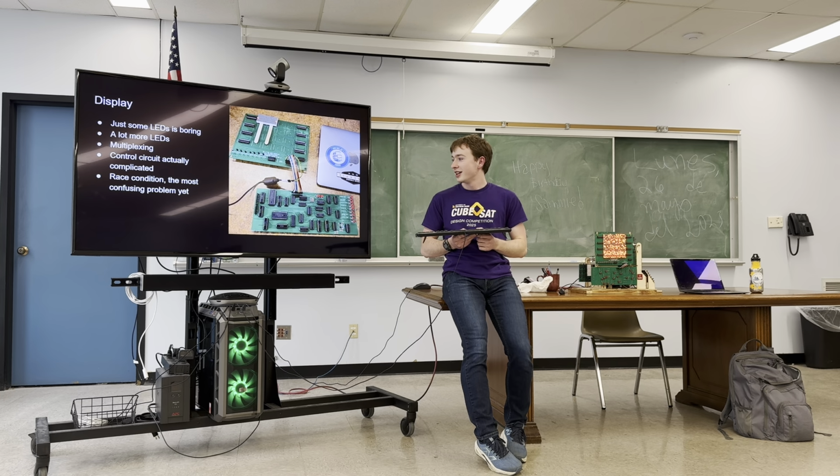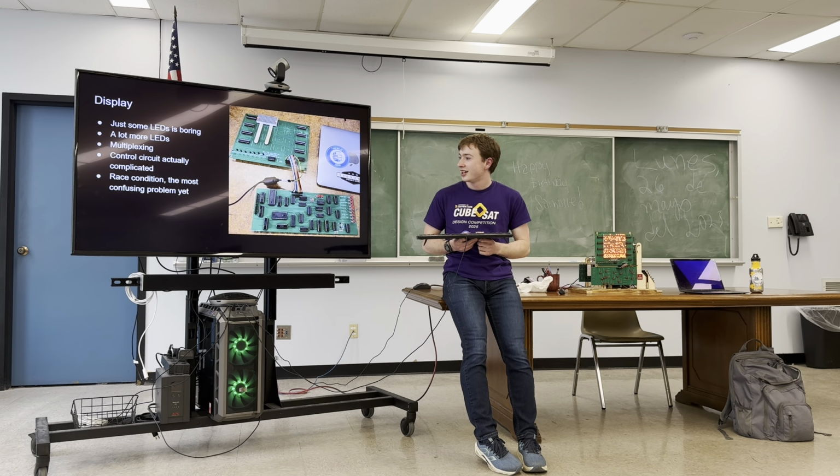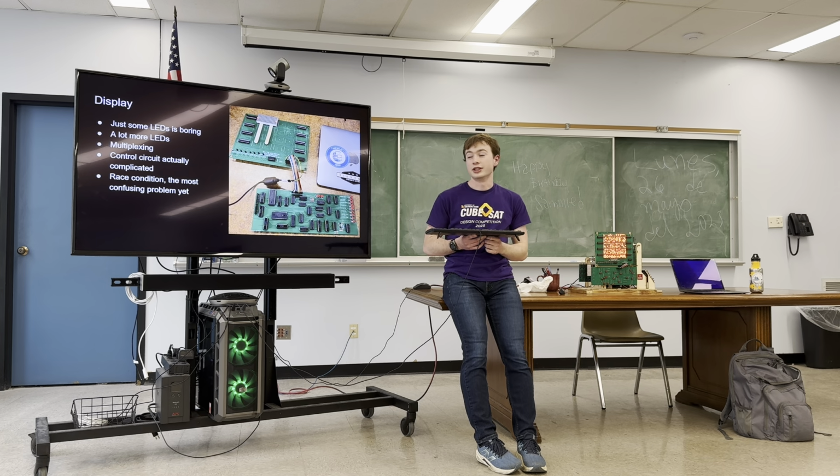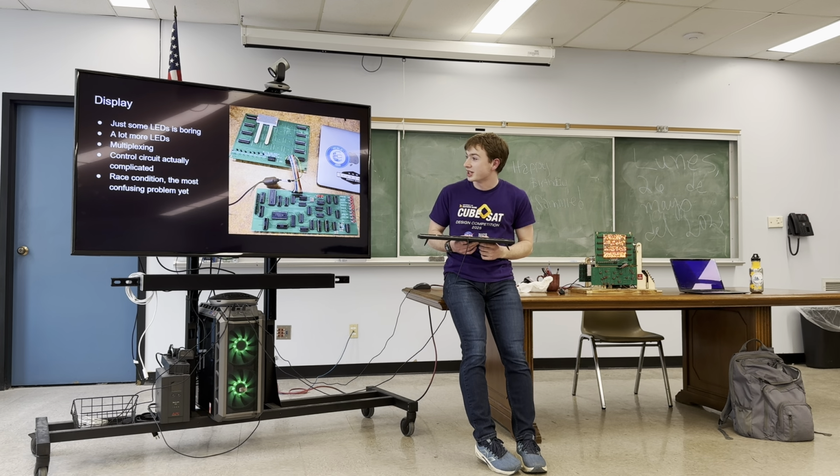So it turns out I don't have the circuit diagram, but there was a race condition where there was some really delicate timing going on, where one thing had to happen before the other thing, and they were really close. The timing was so close that it was affected by the capacitance of a digital signal. So if you slowed it down, it would work. And I did eventually fix it by attaching some capacitors between the signal and ground, which is not the best, but it did work.